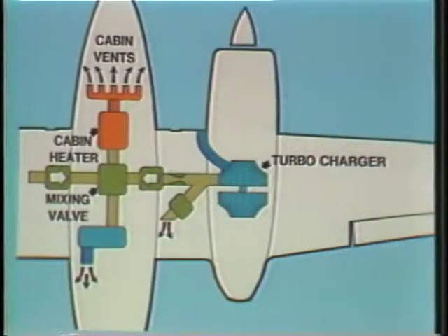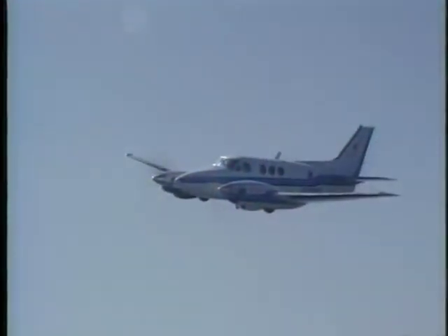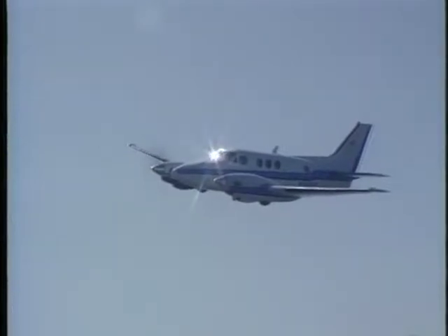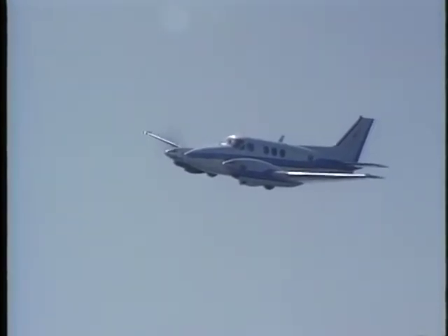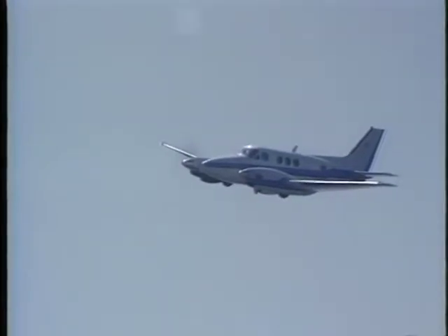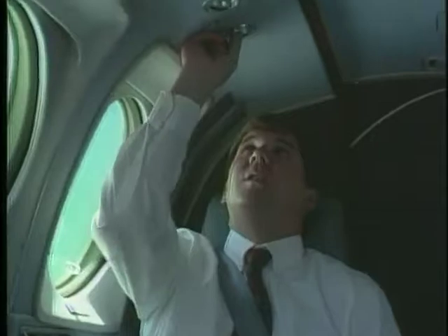An aircraft pressurization system receives compressed air from a turbocharger or the compressor section of a turbojet engine. The advantage of obtaining air from these sources is the fact that the compressor system is already there. The disadvantage is that this air is very hot. Therefore, the compressed air is passed through a heat exchanger to cool it down.